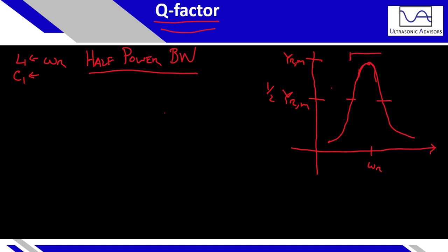And this frequency separation compared to the resonant frequency, so we'll call that delta omega, which is a delta of these two values here, divided by omega r, which is the resonant frequency, as calculated by the real impedance, then gives you directly the quality factor.